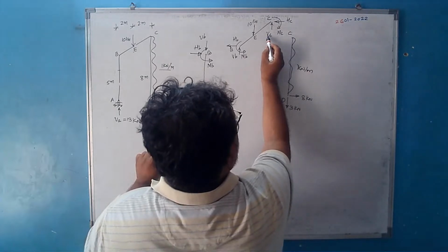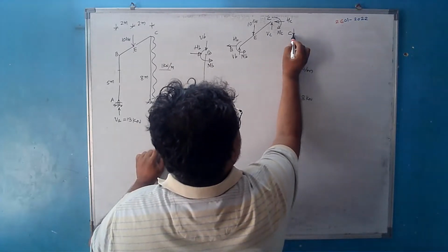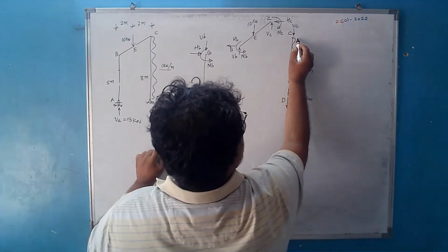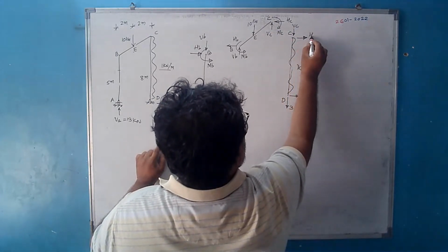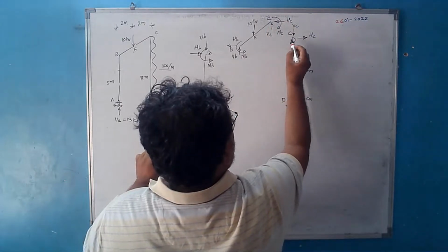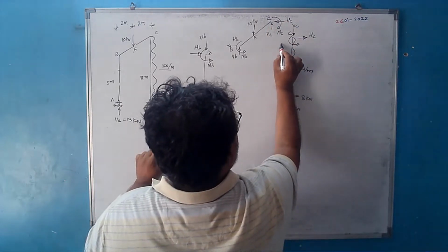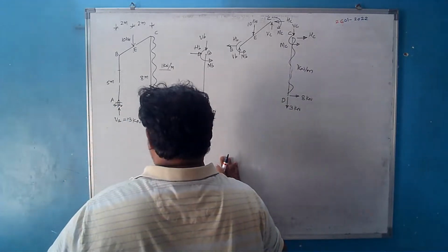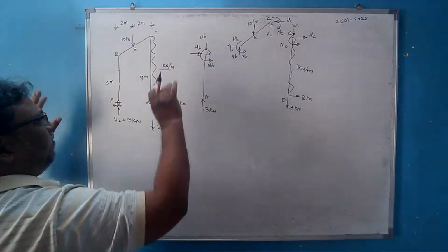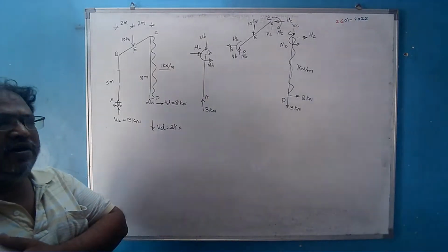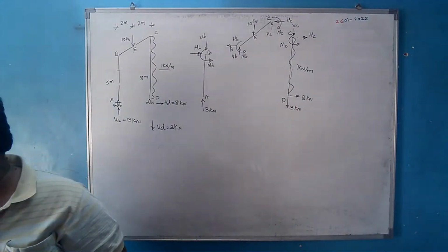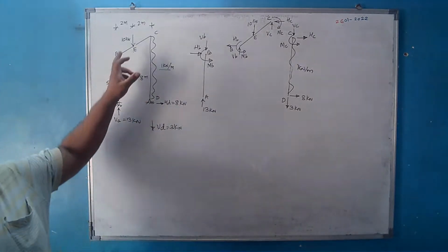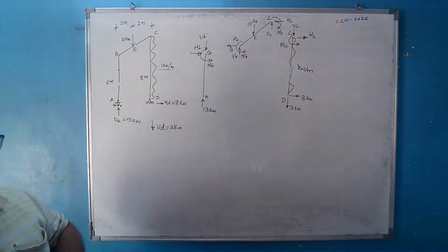And whatever vertical is considered here, I will consider the opposite of that. So this is VC. This SC was considered left, so here SC must be considered right. This moment was considered clockwise, so here the moment is to be considered anti-clockwise. That's all. And we have separated the elements into a number of parts. For our syllabus, we are having portal frames, 3-member portal frames. So these are the 3 members, and we have separated them.